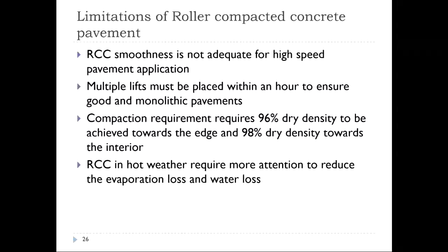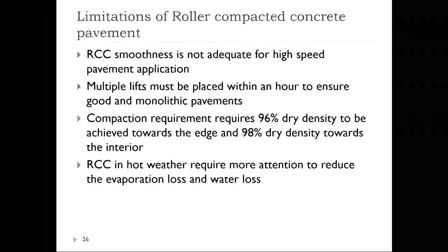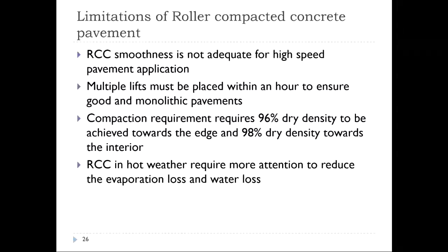Now, in the case of multiple lifts, just because we have limitations in terms of compacting a 150 mm thick layer as a monolithic layer, we may go for multiple lifts. When we go for multiple lifts, they should be placed without much delay to obtain this as a composite section. This is one very important thing.